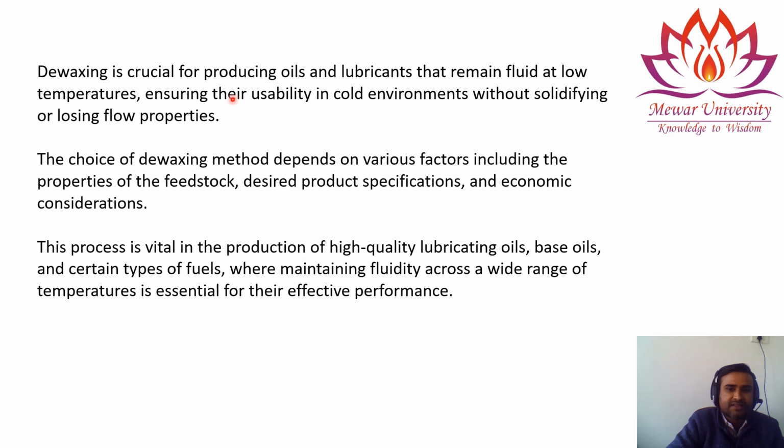Once wax is inside, the flow property is lowered. In cold environments the wax creates a problem and the fluid loses its flowing property. The choice of dewaxing method depends on various factors including the property of the feedstock, the kind of feedstock available, the desired product specification, and economic considerations.